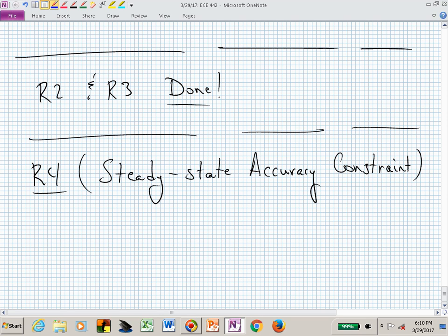In some cases, we may not impose any steady state accuracy constraints. Remember our first design? I injected a 1, and where did I end up? You remember from last time? We went below, didn't we? We went to where? -4? So there we weren't concerned so much with steady state accuracy, but we might be.